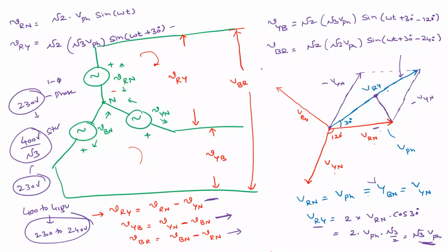In the previous class, we started discussing three-phase circuits. As we already discussed, the three-phase may be connected in either star or delta. Right now, we are looking into the star connection. In the star connection, the phase currents and line currents are the same, but the phase voltage is 1 by root 3 times the line voltage, and the line voltages are advanced by 30 degrees.